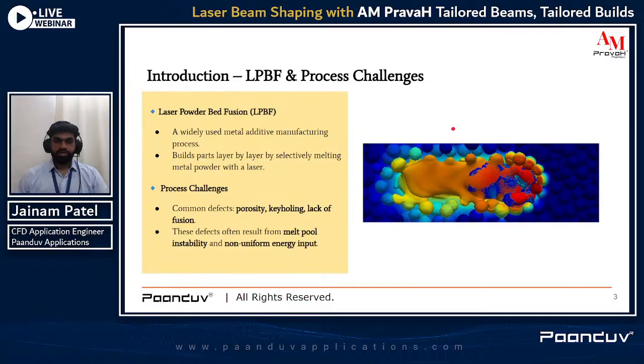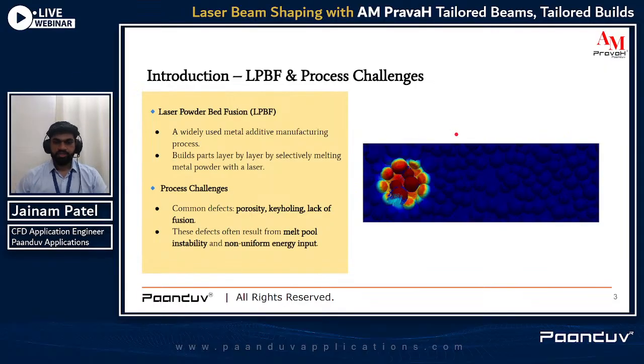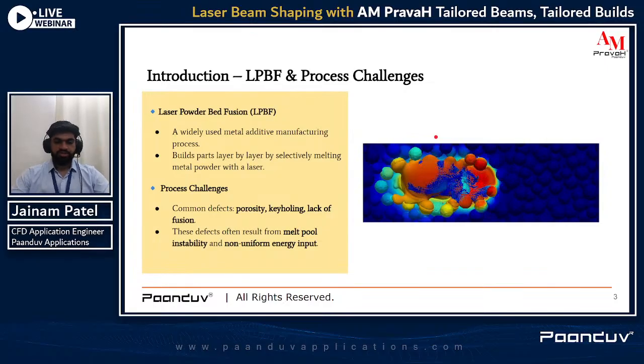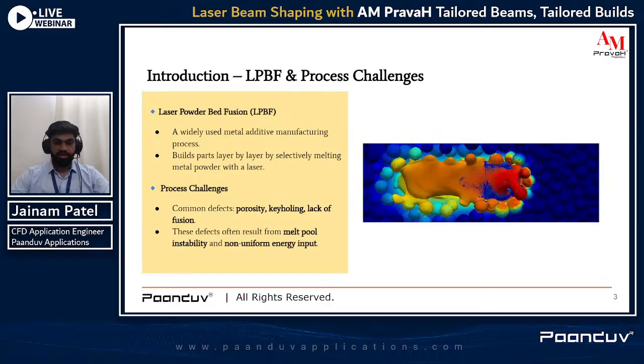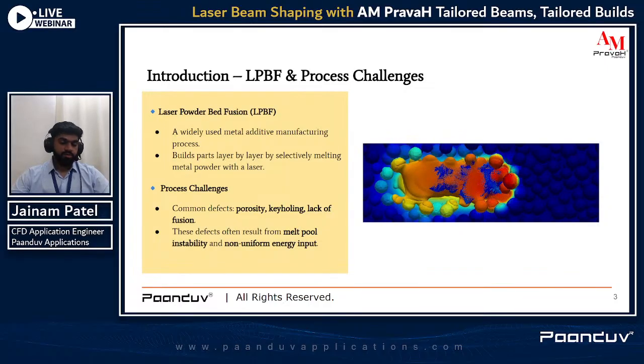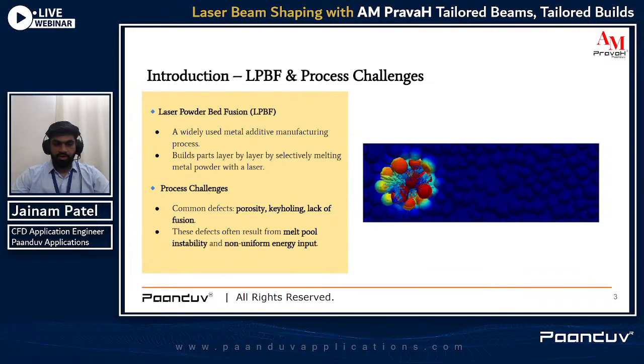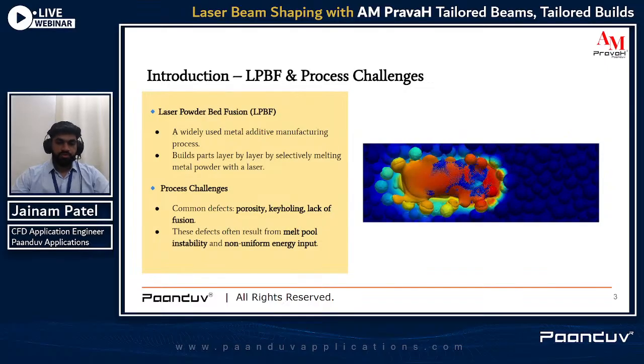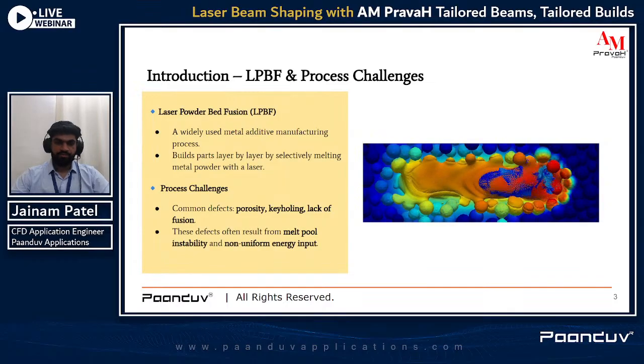Let's begin with the introduction about LPBF and process challenges. Laser powder bed fusion, or LPBF, is a widely used metal additive manufacturing process. It builds parts layer by layer by spreading a thin layer of metal powder and selectively melting it using a high powered laser. As each layer solidifies, a new layer of powder is applied, and the process repeats to form complex 3D parts directly from a digital design.